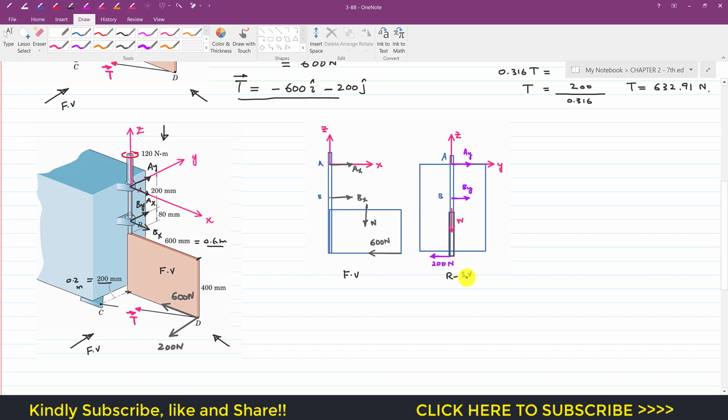Similarly, in the right side view, we will be able to see this 200 Newton component, which is parallel to the y-axis, since this right side view gives us the yz plane, the y and z axes. The x-axis is out of the screen. So we will be able to see this 200 Newton. The 600 Newton is into the screen, and we will be able to see this By component and this Ay component. The Ax and Bx components are out of the screen, and the weight of this plate is acting in the negative z direction, which we will be able to see like this.